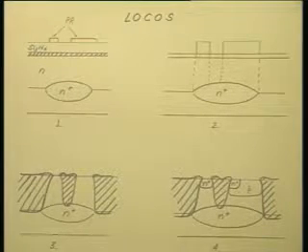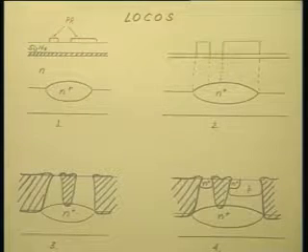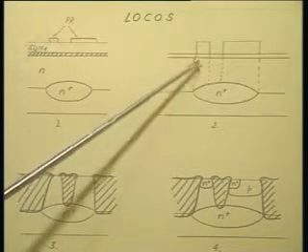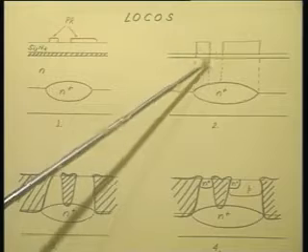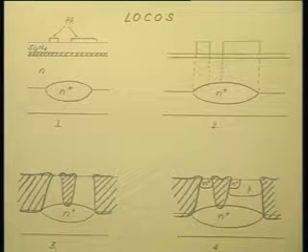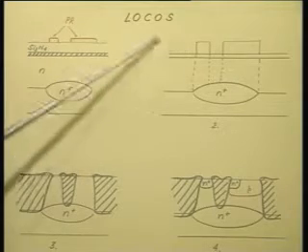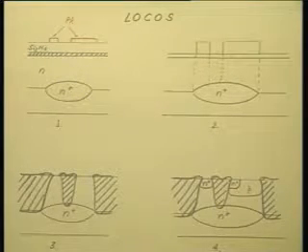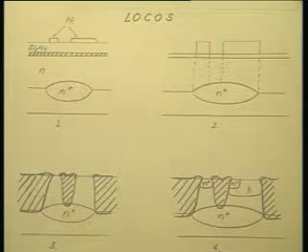So, instead of that, what is done is one additional step, as I have shown by this dotted line, you etch a little bit of silicon. That is, whatever is the oxide thickness you want, you etch the silicon down by about 0.55 times of that.